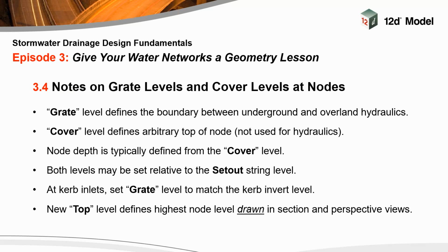So the depth of a node is typically defined from the cover level down to, say, the sump level, or the depth to invert of a pipe is from the cover level of the node to the invert level of the pipe. So depending on how you want to define the depth of a node, and again, that is arbitrary, it's up to you or your verifier, that may determine where you set your cover level to.